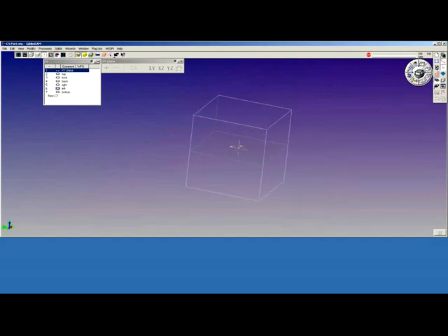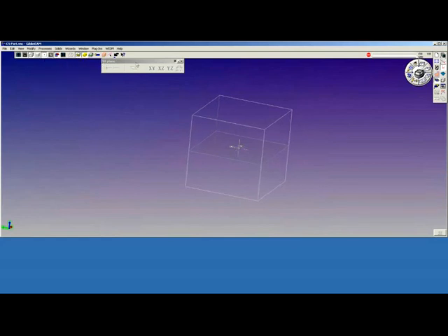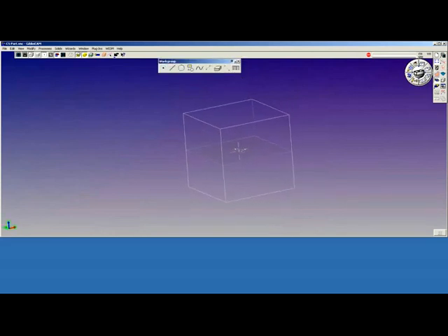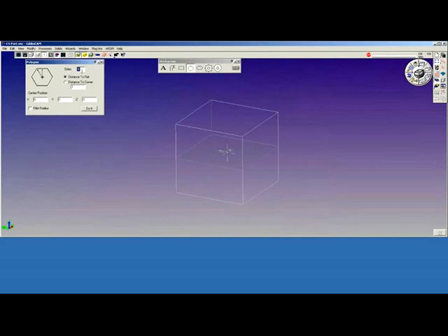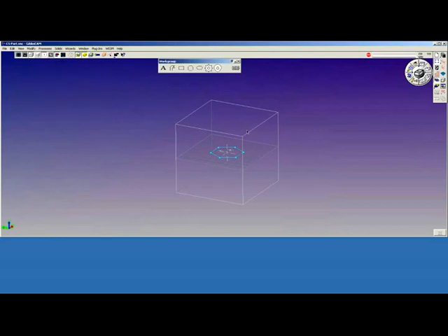I'm going to close my CS dialog and my CS palette and open my geometry creation palette. I want to place some geometry in this central coordinate system. And I'm going to do it with a simple shape, polygon, something basic, 6-side hexagon, distance to flat. Let's go 0.75 and center position 0, 0, 0. We'll say do it, and it places the geometry right on center.